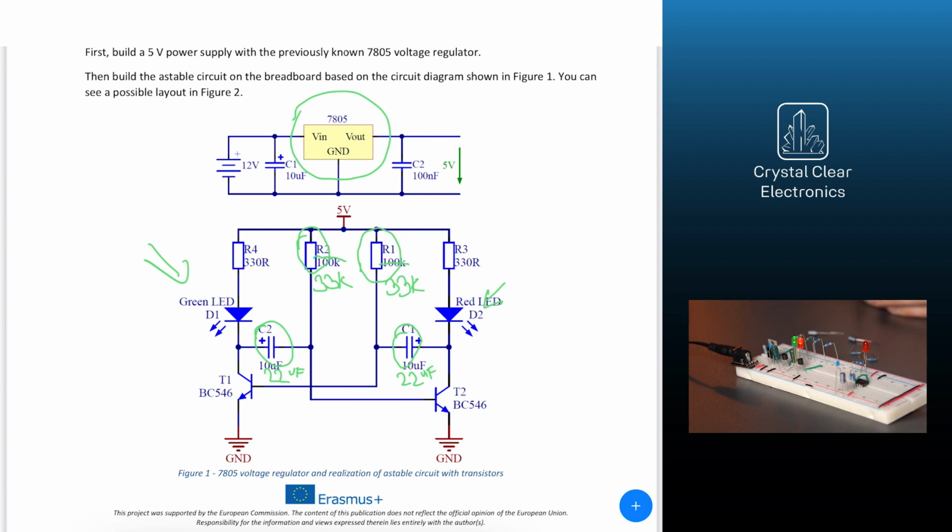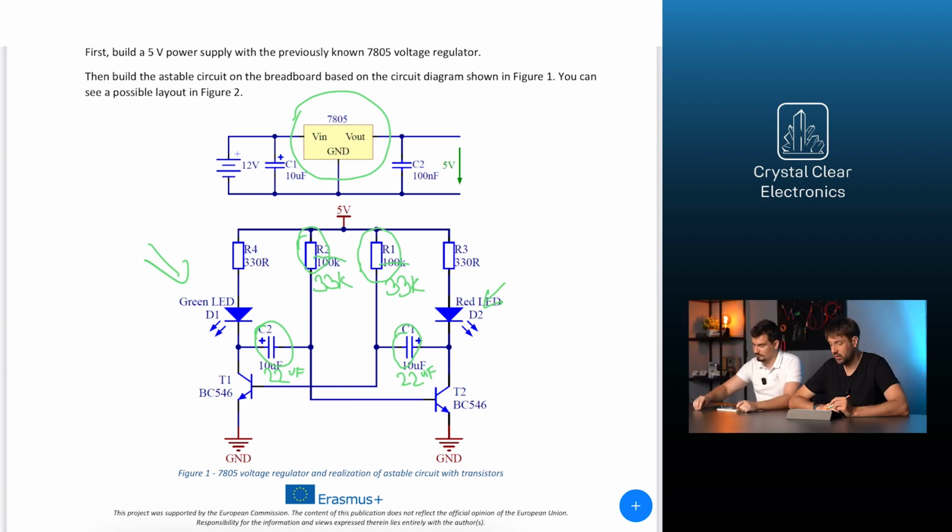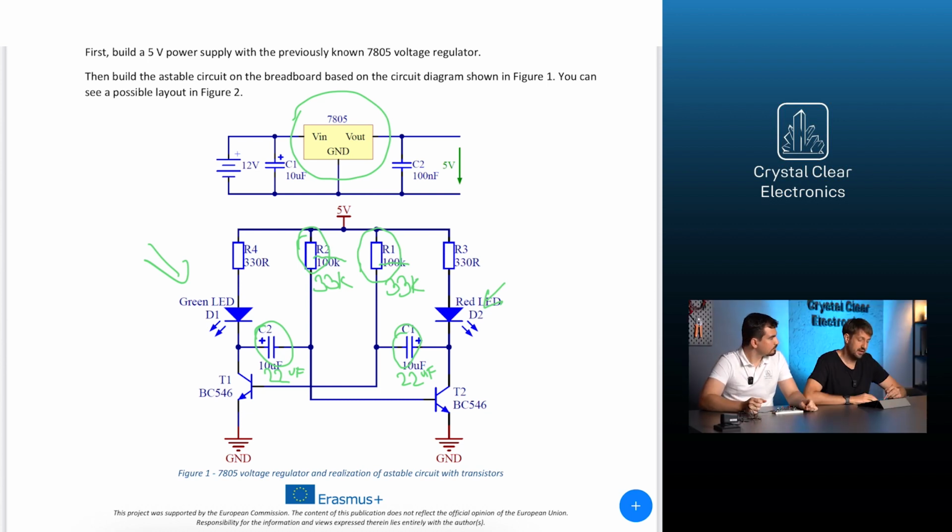If you try to replace R3 and R4 resistors, for example with 1 kilo-ohm, the blinking frequency will not change, but the brightness of the LEDs will be different. Try strictly with higher values, because a lower value than 220 ohms can damage the transistor and the LED.